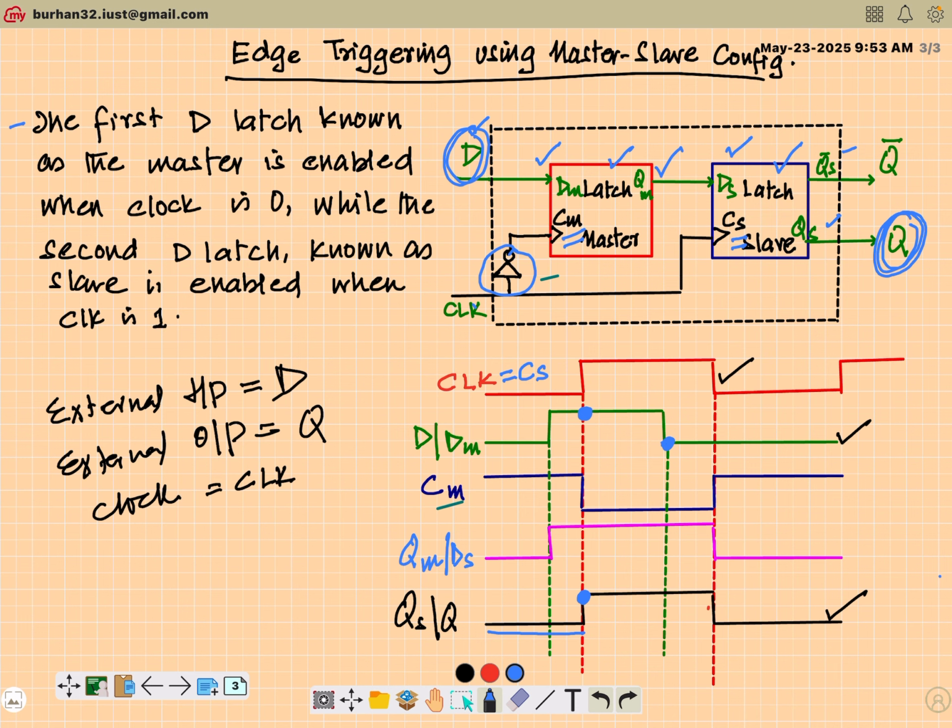Both will store one bit, and both will have the same problems which are there in the SR latch. Only the difference is the way they react to the clock. Right? So immediately after this, we'll be taking another storage element that goes by the name JK, and we can have a JK latch, and we can also have a JK flip-flop. The only difference is that if it is a JK latch, it will respond to the level of the clock, and if it is a JK flip-flop, it will respond to the edge of the clock. Right? So we'll end this video here.